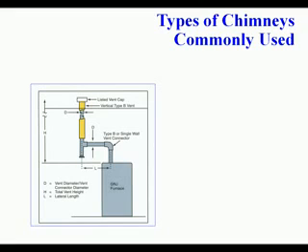Exhaust gases are removed from conventional furnaces through a vent system consisting of a flue pipe that is joined to the chimney and vented outside. Flue pipe temperatures can reach between 500 and 600 degrees. The efficiency of this furnace is reduced by 30 to 40% because its heat is exhausted out of the chimney.